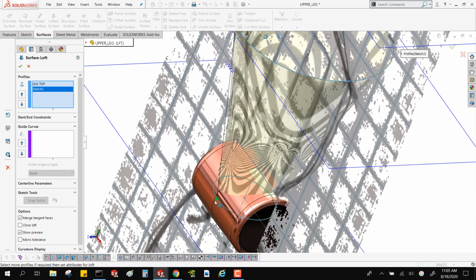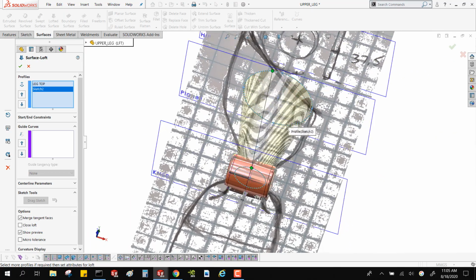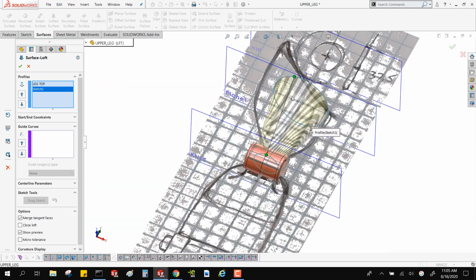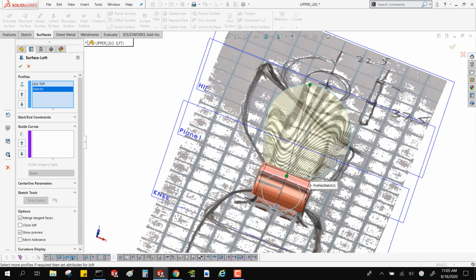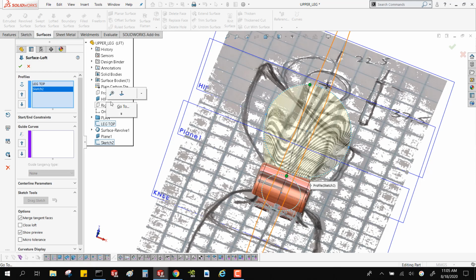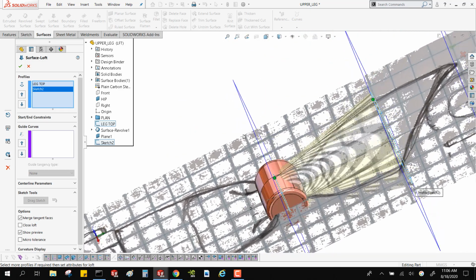So in this one, at least I've got some geometry that I can use as sort of homing where exactly the heck I am. Like that mid plane or that axis. And so you want to get it straight up and down. I'll show you a little later. You can also go around in a circle. If I have any guide curves, it's better to use the guide curves along than it is to use the circular ends, just because the circular ends run the risk of that twist happening. So I've got it going straight from the front of the knee up to the front of the thigh.